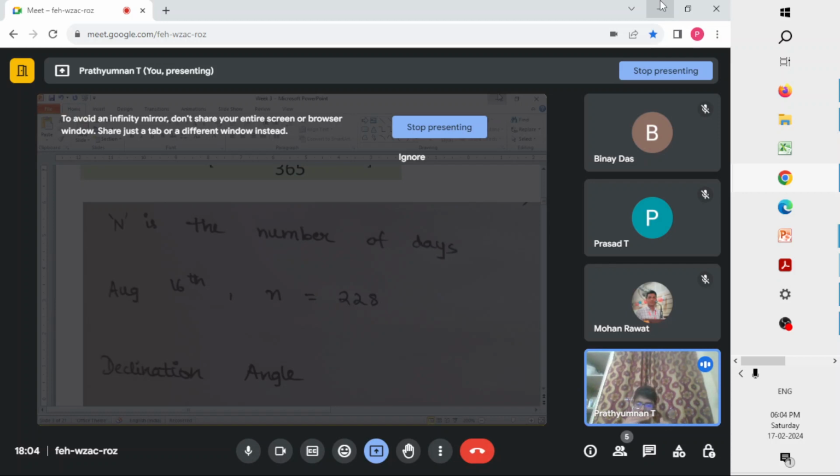So between this glass plate and the absorber plate, it is only filled with air. This absorber plate is coated with black, a kind of selective surface, to increase the absorption capacity, that is, to increase the amount of solar radiation that can be absorbed by the plate. The heat the absorber plate has gained goes to the fluid tubes.